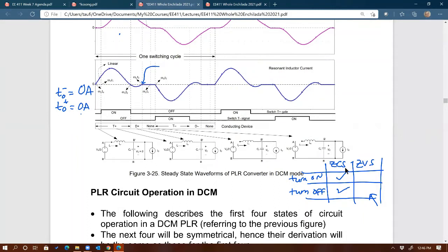Yeah, so you need to look at when we turn off the switch. Right here. This is when we turn off the switch, so call that T0. What happened with the voltage across the switch at T0 minus and at T0 plus? How many volts? When the switch is conducting, there's 0 volts across. Okay, so which one is that? T0 minus. T0 minus is 0, okay, very good.